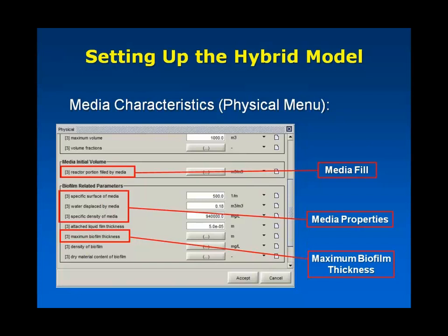This generally is a parameter which, when I'm doing my jobs, I leave at the default to start with and then see how the calibration goes, and then we can possibly make some changes to it downstream. This is a parameter that we've had some experience with, which can differ significantly between municipal and industrial treatment systems. So biofilm thickness may be a relevant parameter in some industrial treatments, specifically if you have high rate treatment or a very large amount of substrate to work with, such as food waste treatment.